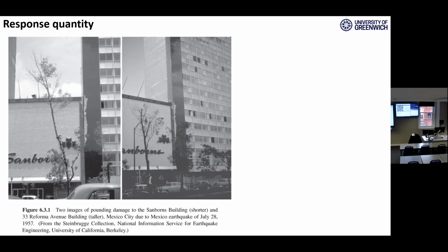They're just touching each other, and it's called impact of two structures, or pounding. They pounded into each other during the earthquake and caused some local collapse between the structures. So if the structures are very close together, it's more likely to have a pounding effect during the earthquake.